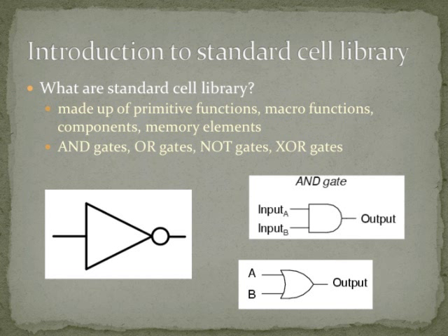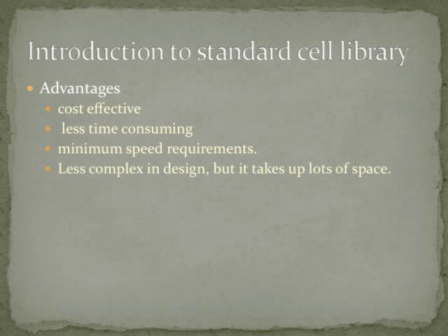characteristics for use. There are many advantages for using standard cell library, which includes making the cells cost-effective and less time-consuming. They are also able to fulfill minimum speed requirements. They are usually less complex in design, however, it takes up a lot of space.